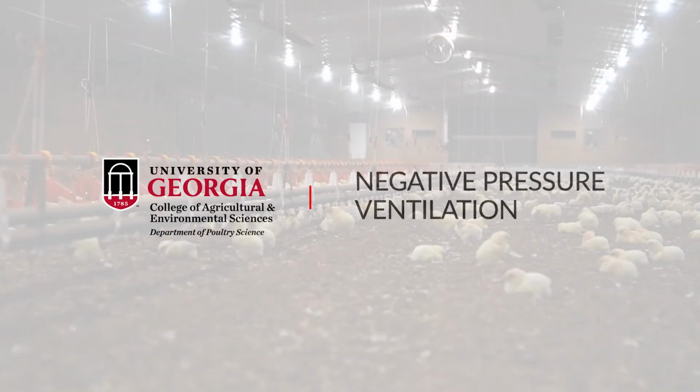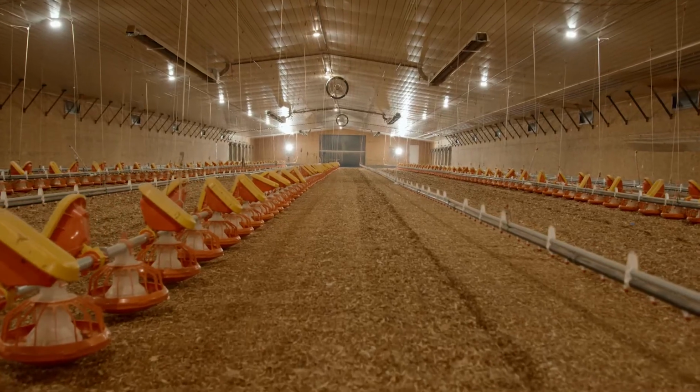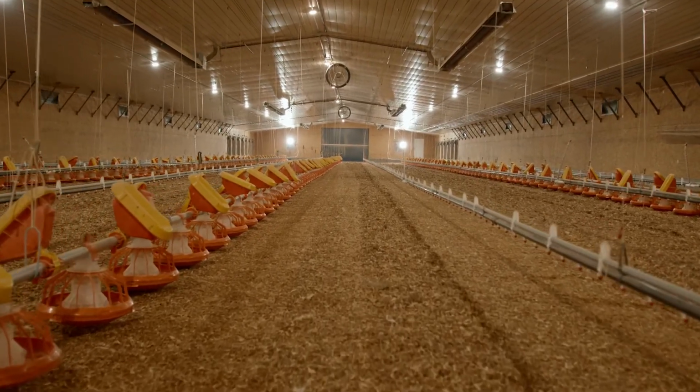One of the most important aspects of an environmental control system is we need some way to bring in some fresh air. We need to bring in fresh air, not just to control air quality to keep our birds healthy, but we also need to be able to bring in fresh air to control the house temperature, because the hotter it gets, the more heat the birds produce, the more fresh air we have to bring in to maintain a consistent temperature.